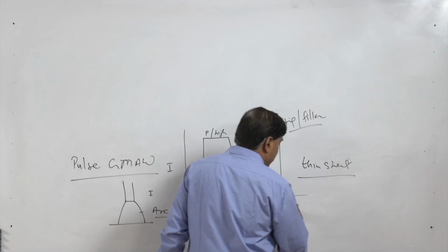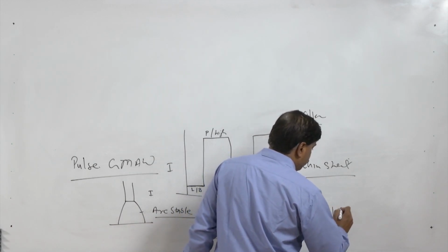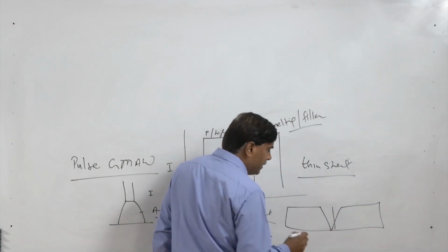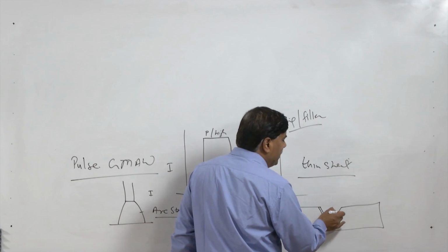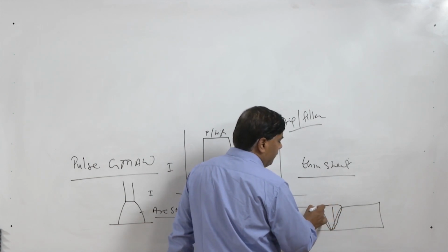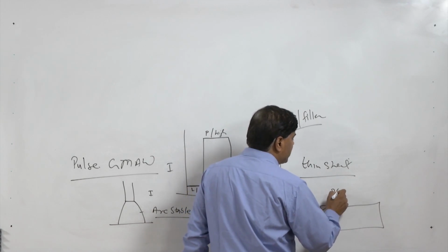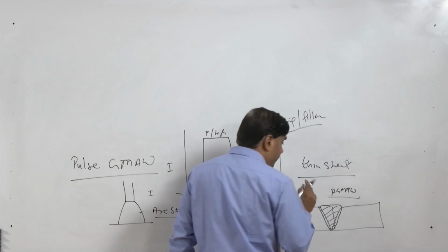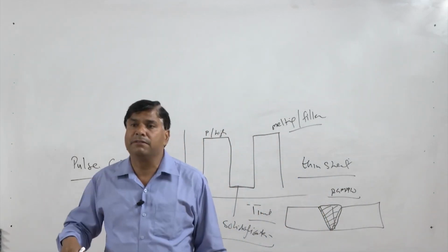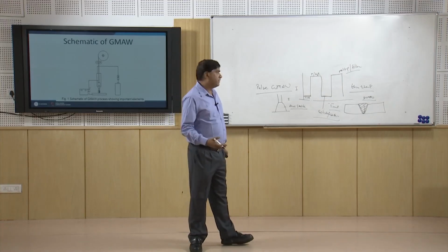We want that even if the sheets are not very thin, but the metal which is being welded is very sensitive to the heat. So the heat delivery to the base is very less, and very little melting of the base metal takes place for development of the joint. In this case also the pulse GMAW helps a lot, because it effectively reduces the heat being delivered for the melting of the fixed surfaces and development of the weld joints.